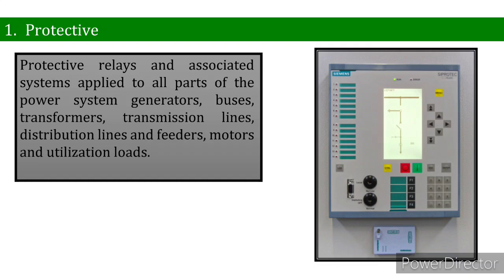So in different countries, there are different voltage levels like 765 kV down to the service level of 480 volts or 220. In general, distribution equipment below 480 volts and in some places 220 volts is protected by fuses or protection devices that are integral with equipment.